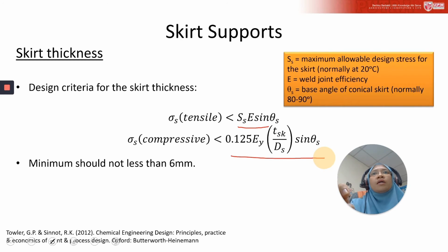And then the minimum thickness, you must remember that it should not be less than 6 millimeter. All right, if let's say you calculate and get less than 6 millimeter, that means there is something you need to reconsider in the parameters that have been used.